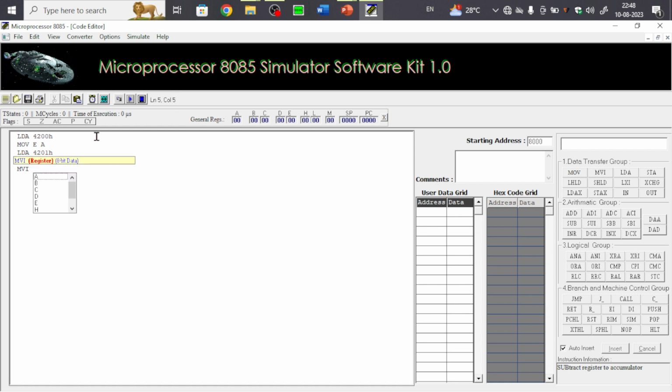Now we have to clear the other register in the register pair. So move immediate: here we are using the D pair, so use the D register, MVI D, 00. Then clear the HL pair also, LXI H, 0000. Enter. Now we will implement the addition, DAD with the register pair, here DAD D. Then decrement, DCR, the B register. Then jump no zero, JNZ, to the label repeat. Then SHLD, store the result in the external memory address 4202H. Then halt. One more thing, the label is missed here. Type repeat colon and a space, like this.